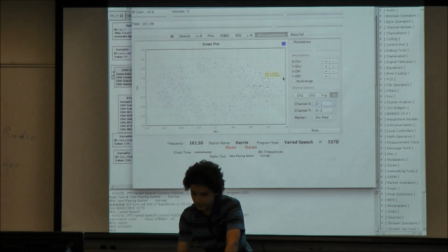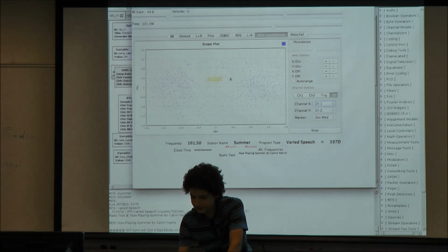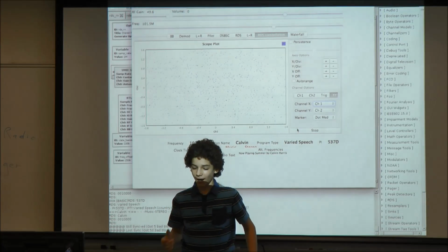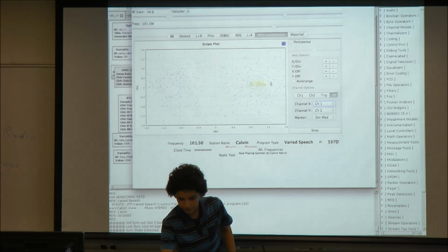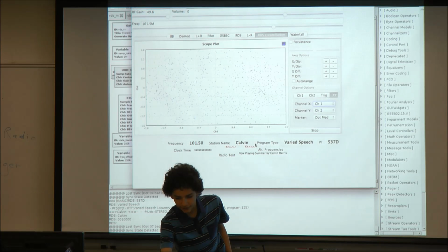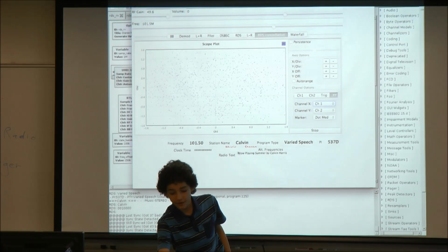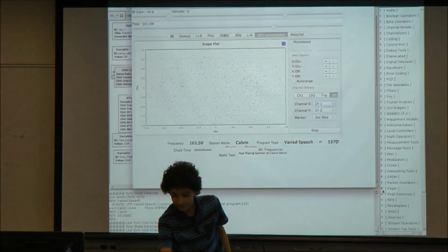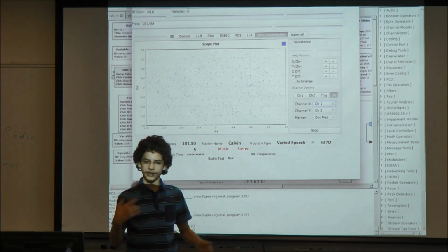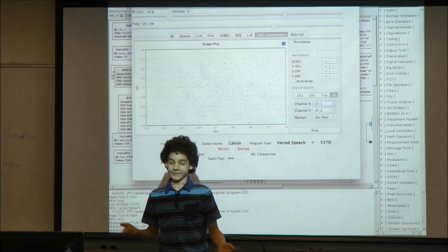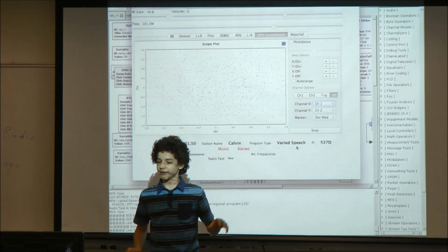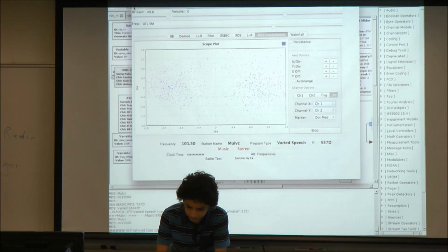We look at our constellation. You'll see there's better separation. Our house is near South Mountain, so that's probably why I get nice reception. You'll have a cluster of points here and a cluster of points here. But if you notice, it is decoding this. The station is Calvin something, and the text they're sending is now playing Summer by Calvin Harris. There's other data like TP and TA says it's a traffic program, so they transmit traffic data, and TA is it's actually sending it. SPTY is some other data sending thing, and you all see traffic through that. But yeah, so there's that.